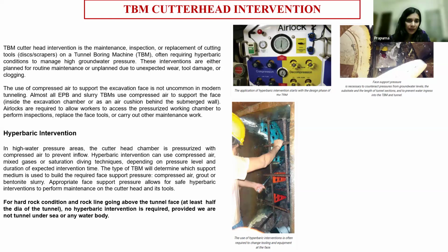So even if the segments are cracked, we can't do anything directly. You have to seal the cracks. You cannot replace the cracks. You cannot replace the segment.